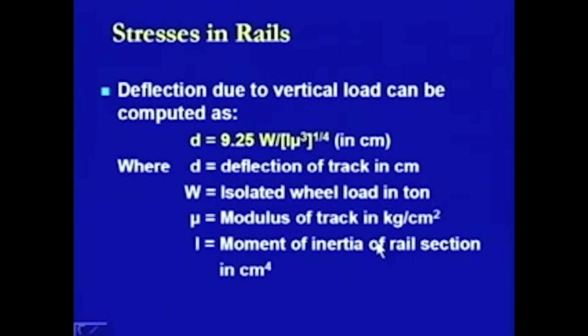This is one aspect, that stresses are being induced, but not only the stresses; there are other conditions, that is, deflections may also be induced because of the loading. When deflections are induced because of the loading, we have to look at the total amount of deflection induced. If the deflection is more than the permissible value, it will cause the failure of the system. Therefore, this value is to be calculated.